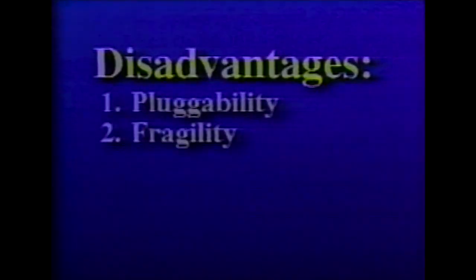Fragility. If the epoxy drain pores become plugged during the backflush mode, the cake will have a high pressure differential across it with no upper support.